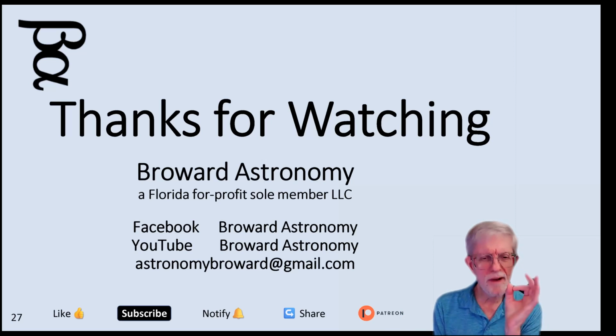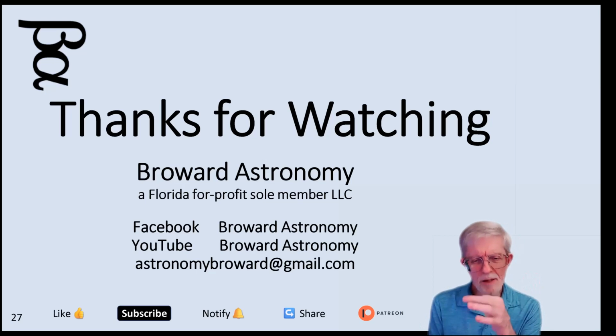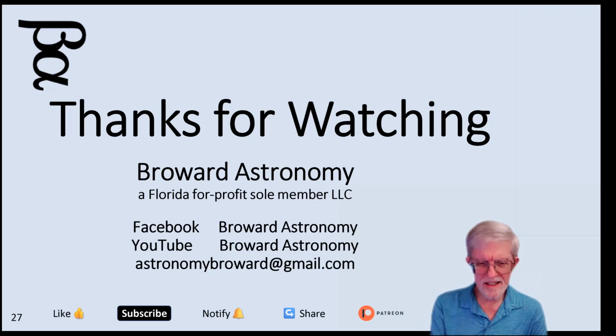And they're large microphones. Whenever you see one of these large electret microphones, this is the element that would be inside of it. But that doesn't produce a digital signal. That just produces an analog voltage out. And then you have to have another analog to digital converter and amplifier on the back end that is going to be more sensitive. And I may have to resort to that, but I won't know until I try.